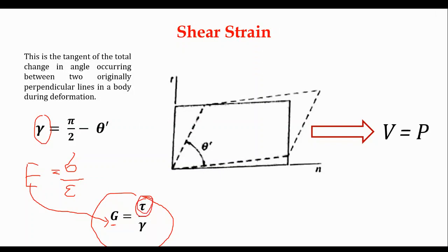This is a measure of how tough your body is with respect to shearing. For example, if G is large, you do not deform easily. Even if you are pushed, you will not sway like this, you remain intact. If you sway, then G is probably small.